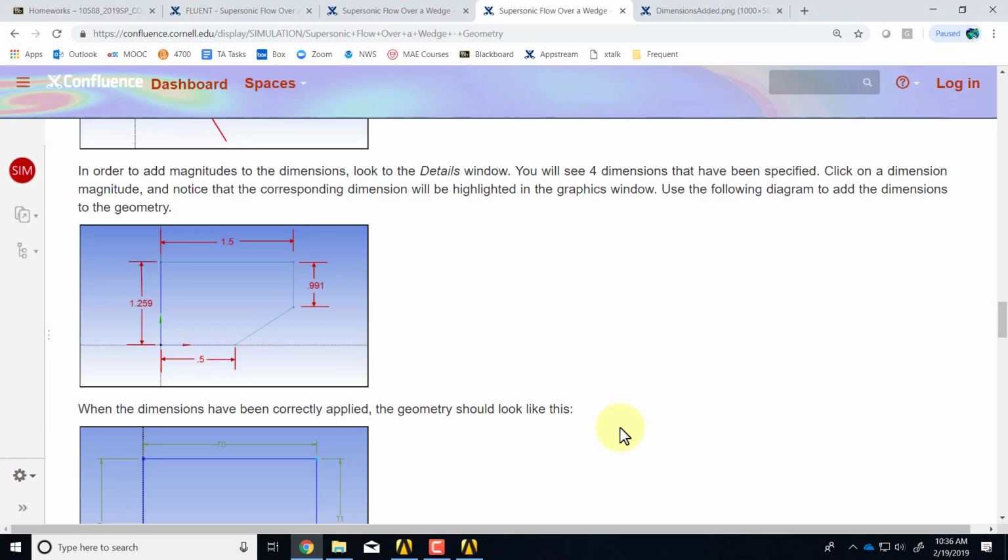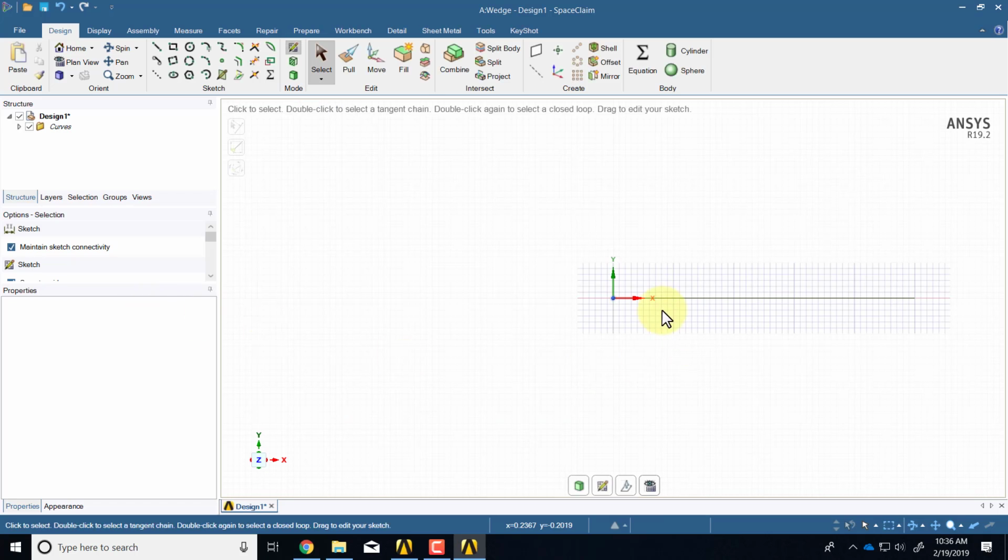Let me go back to the figure. Let me go and draw this line, and I will round this off to 1.3. It could even be 1.5, but to keep it consistent with the previous version of the geometry step in the tutorial, I will round that off to 1.3. So I will go again, I'll say line, snapping to endpoint, start over there, and make sure you're getting the 90 degrees, hit the space bar, and enter 1.3.